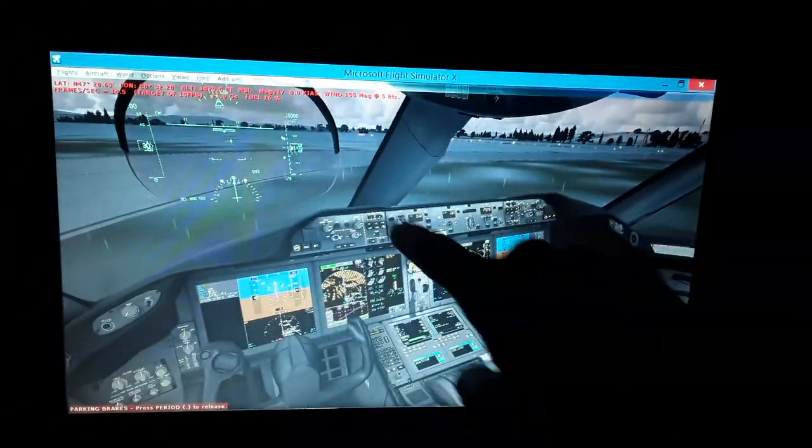The autopilot flight director system panel. So I'm going to set the autopilot flight director system panel. We have the heading, and the bank angle limit. We have the vertical rate of climb and descent of the aircraft, up to 10,000 feet per minute, and also the altitude select. You can select an altitude in thousands of feet, hundreds of feet, and select the mode for that.